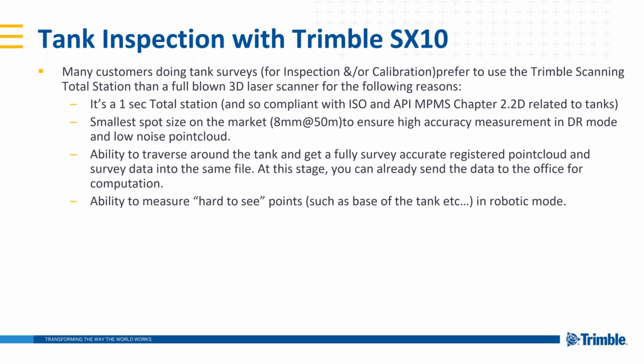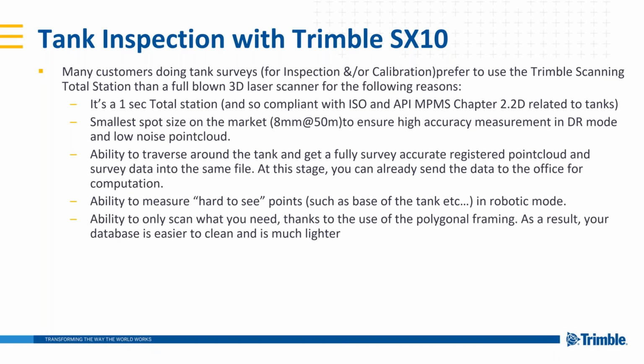A lot of the tank facilities here in the U.S. are located around the south where we get a lot of precipitation, a lot of rain. So you have water standing because you have these secondary containments built around the tanks to hold liquids in. So laser scanners, because they're light, they can reflect and do weird things when they hit water. So having a total station will allow you to get some shots in those difficult areas as well.